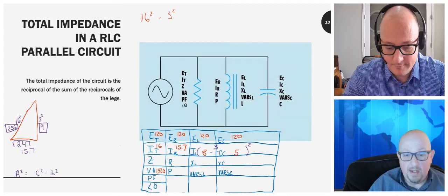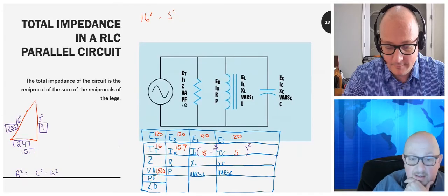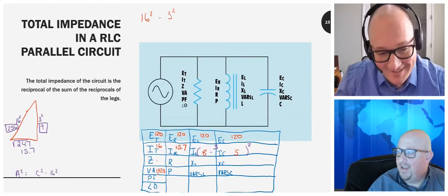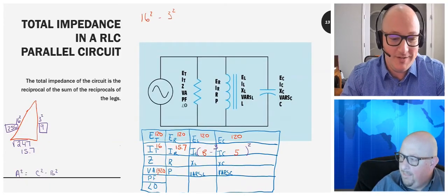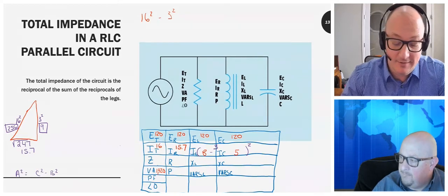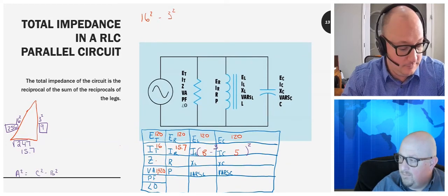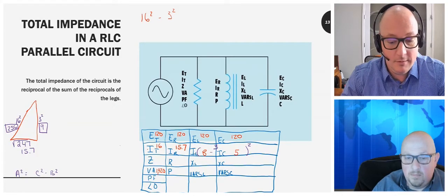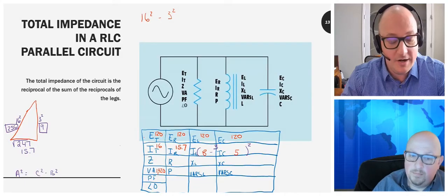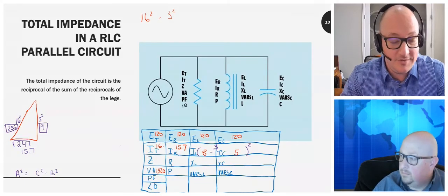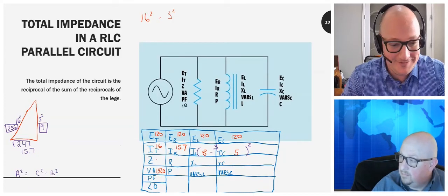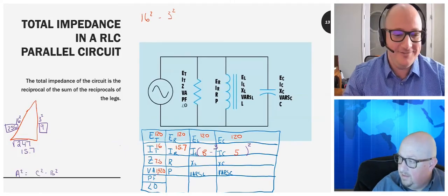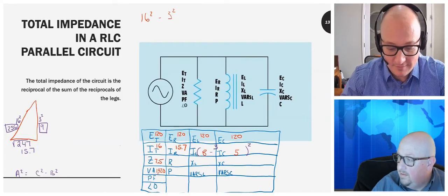And I'm just writing down what you're saying. So I assume that was the VA. Yes, it was. Now we can solve for total impedance by taking the voltage over the current. This is good. 7.5 ohms of impedance.